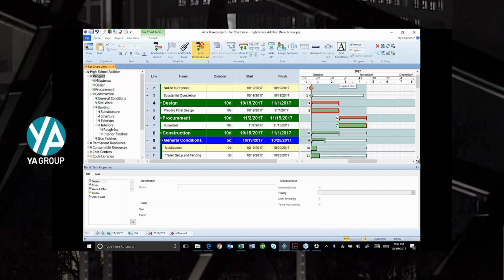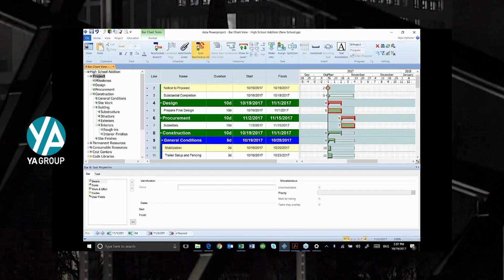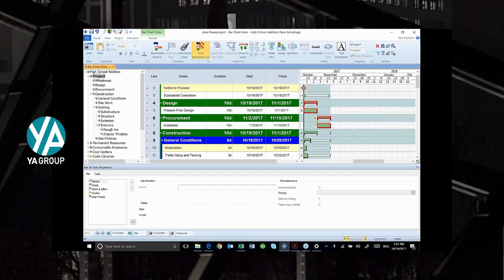Also notice when I'm adding my logic, sometimes I'll zoom in on some activities. If I put my mouse up on the top in the timescale area and put my mouse over one of the little red tick marks, I can click and drag. That zooms out, zoom in. If I move my mouse up another row to the top and select, it turns into a hand that'll slide the timescale back and forth.